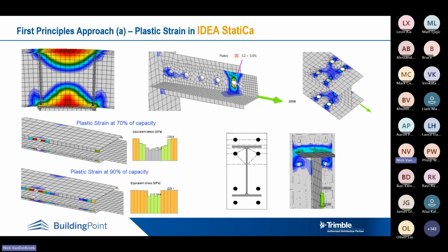So we're in a yielding plateau at this level. So a little bit less load can change the extent of plastic strain maximum quite a bit. And similarly, a universal column with bolt holes, we recognise there can be stress redistribution around bolt holes and so on, even if it's symmetrical like this. And we have the expression I mentioned before for the capacity to the code, or we can check the plastic strain in the software. And so too with welds, we see at different load levels some plastic strain developing at the ends of a longitudinal weld.